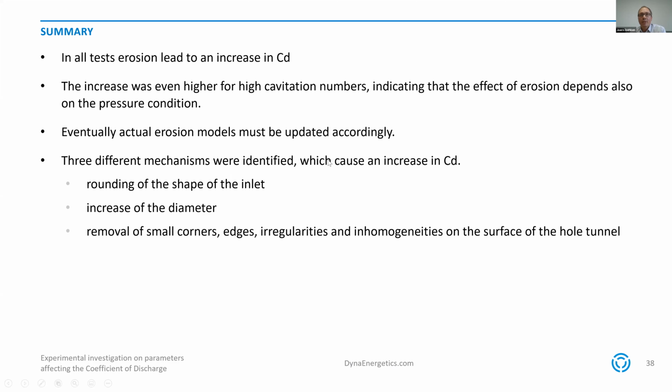In the erosion tests, we've seen that erosion leads to an increase of CD, which is not surprising. But obviously, this effect of erosion also seems to depend on the cavitation number, and that indicates that the effect of erosion depends on the pressure condition. And so some erosion models should be deduced at the right pressure conditions or must be updated accordingly.